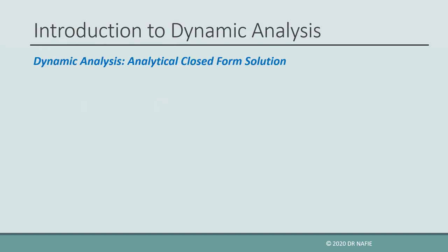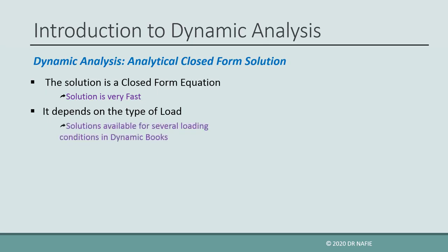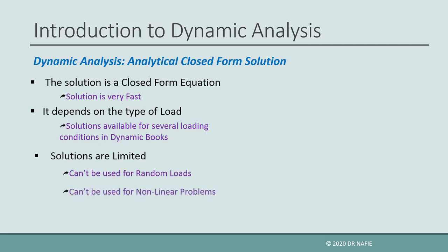For the analytical methods of dynamic analysis, the solution is a closed-form mathematical equation, and therefore it is a very fast method. However, the solution depends on the type of loading. Fortunately, closed-form solutions for several loading conditions on single degree of freedom systems are available in dynamics books. Also, this method is limited in application. It cannot be used for all loading conditions, such as random dynamic load, and cannot be used for nonlinear analysis.